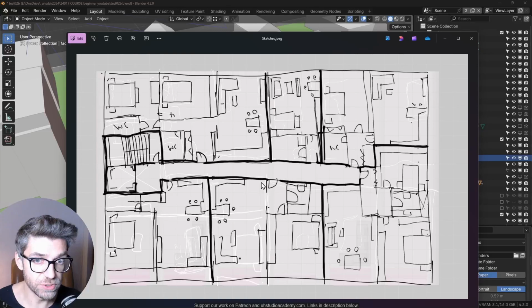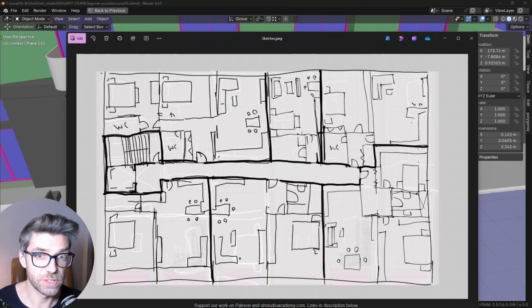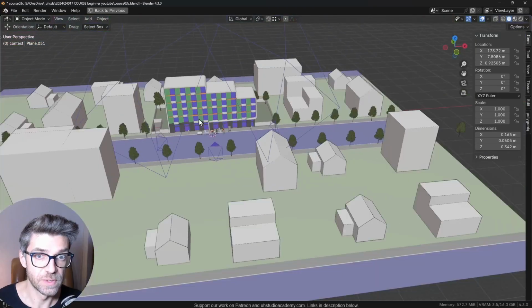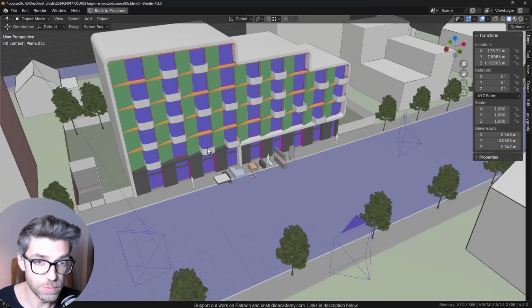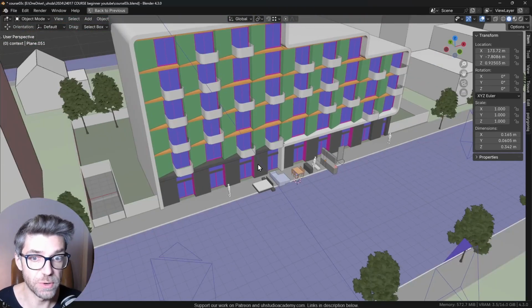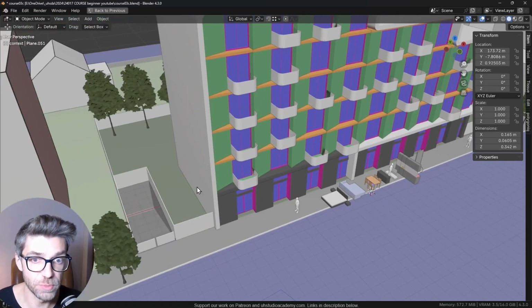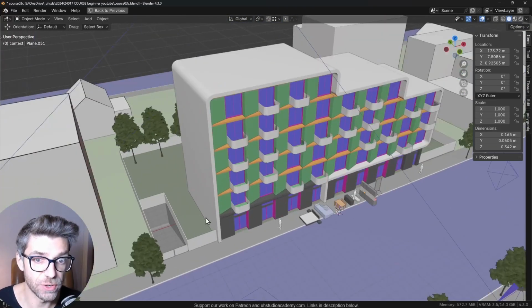Now, in this smaller iteration, this works because that distance is okay from the exit door to here. But in this bigger building, so let's just compare here. The distance from one side, if the corridor runs from here to here, might be too much for the lift to be in there. So we would need an entrance somewhere in the center. How do we enter? Probably not on the side, probably somewhere in the back, I would even say, maybe we have some access into here or to the side.